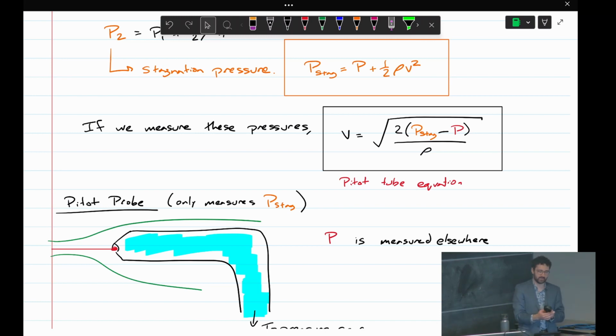I'm not going to pass this around, but there are other ways to measure flow. For example, this is a digital anemometer. It's kind of a little fan, but instead of the fan blowing, you blow on the fan. This is calibrated so that it measures the RPM of the little blades, and then it tells you a given wind speed. I think this is more commonly used in HVAC and things like that. But there are other ways to measure flow is kind of the story there.